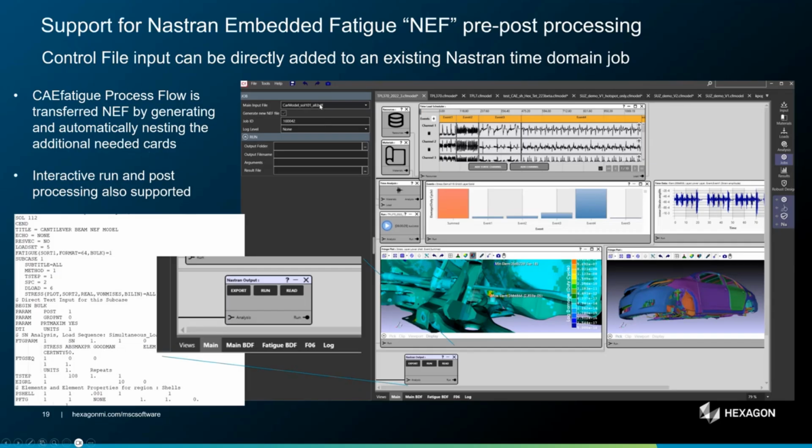So you start with a PDF that is maybe a solution 101, and you can add fatigue loads and fatigue cards and material cards through CAEfatigue. So essentially, CAEfatigue increments and exports a Nastran input file that also includes the fatigue card. So an initial solution 112, for example, will not have this fatigue card and will not have this FTG parameter or FSEC. They are defining essentially what's required for a fatigue analysis to run.